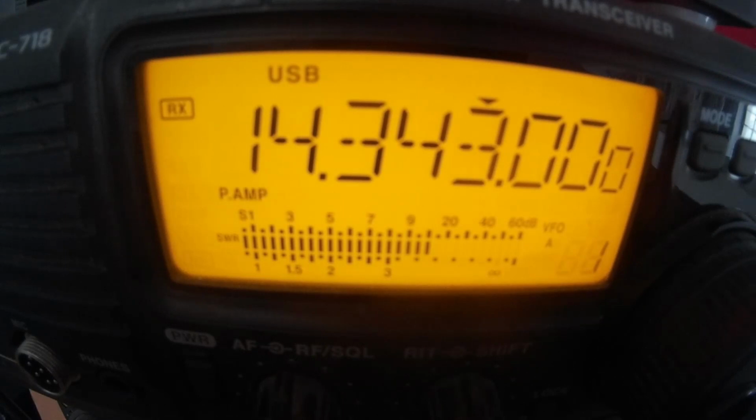Then you can go to the CI5 baud rate. The default setting is auto. You need to make it 96, which represents the 9600 baud rate. Once you do that, you can switch off the radio and switch it back again like I'm doing right now. Okay, so we have switched on the radio again, and now we are at the main screen.